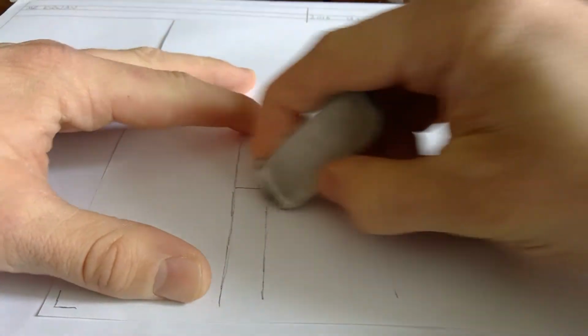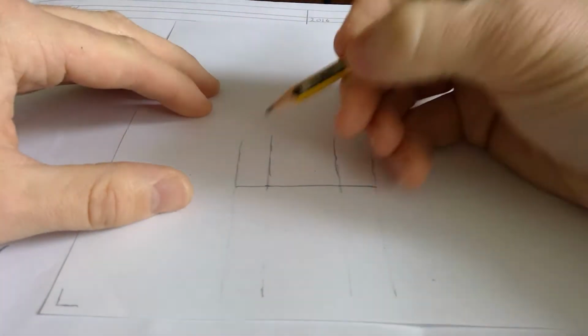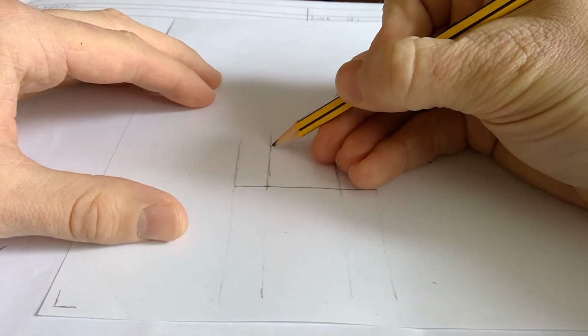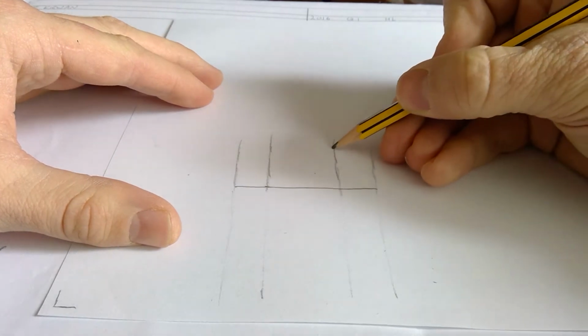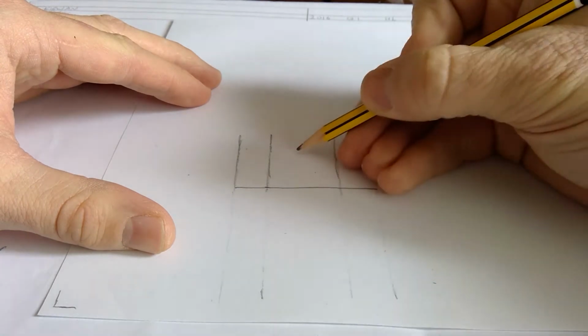About those bits. The window is actually going to go on this space here. Just so you're clear, again, it's going to look quite big when you draw this out. That's going to be 20mm when scaled down. That's going to be 40mm when scaled down, and that's going to be 20mm when scaled down. So external leaf, cavity, internal leaf.